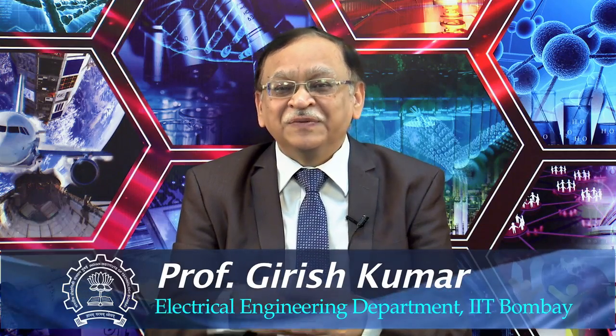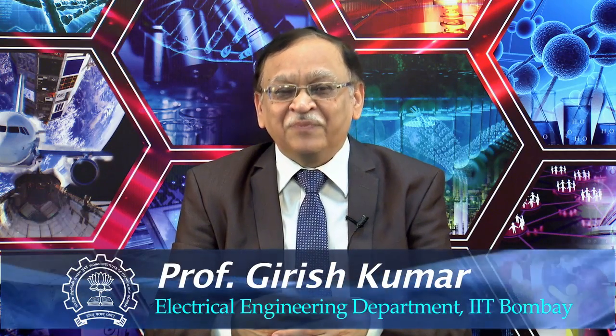And then we took this practical example, and you can see that in this particular example we do not have to do many of the things which I discussed earlier today, but as I mentioned, if you have to design a much lower noise figure amplifier, then you have to draw all those constant noise figure circles and constant gain circles to design an optimum amplifier.